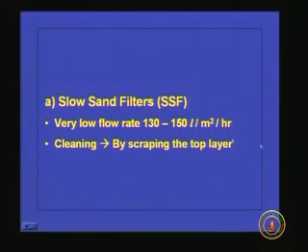So this I have already discussed. The cleaning is by scraping the top layer, and the rate of filtration is very low. That is why the name slow sand filter has come. And one more thing, when we go for slow sand filter, the sand whatever we are getting as the builder's sand or something like that, we can directly use that sand.